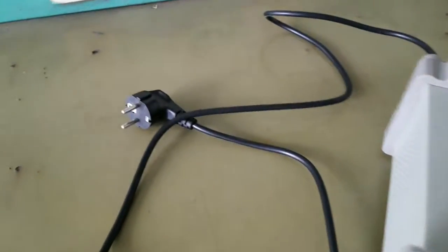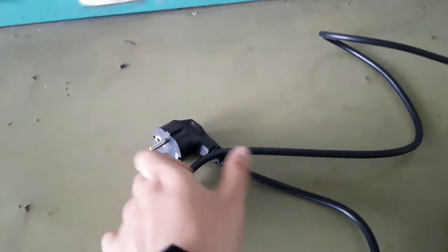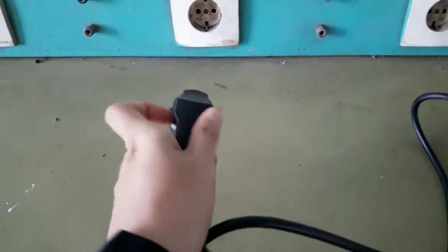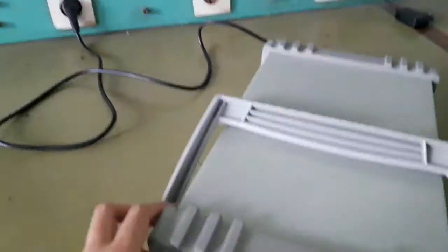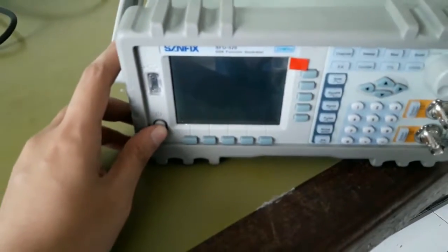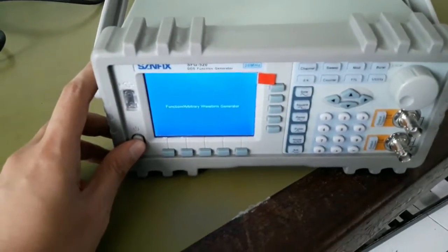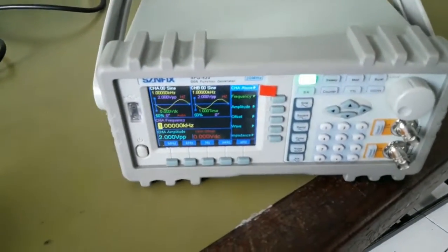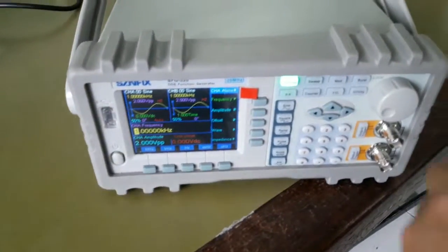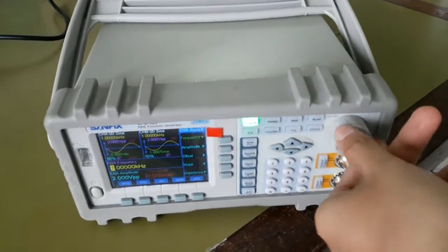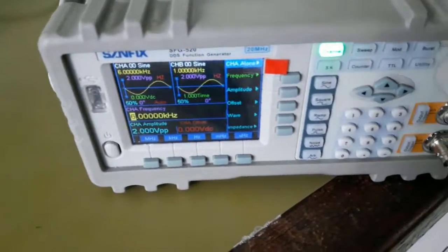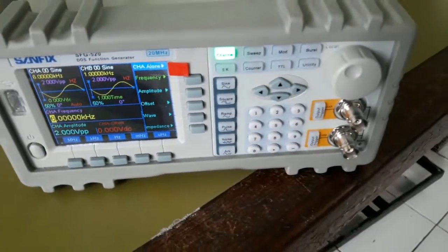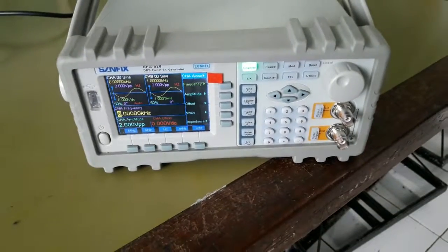And now, I want to tell about how to operate the function generator. First, connect the power cable to the electrical source. Second, click the power button to turn it on, and the LED indicator will be on, and also the LCD frequency display. Third, choose the frequency and waveform, click the button that you want to choose. Fourth, set the multiplier and duty control to identify the waveform. And now you can operate this object.